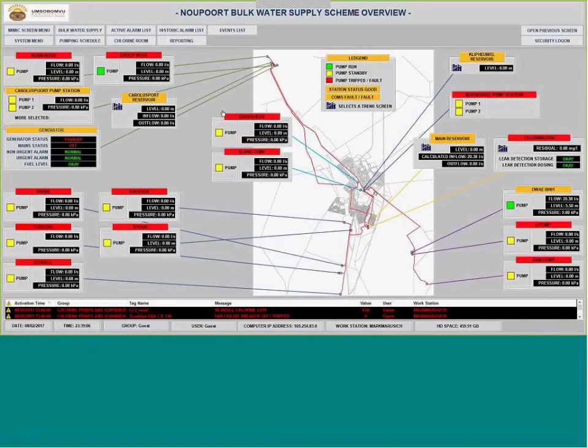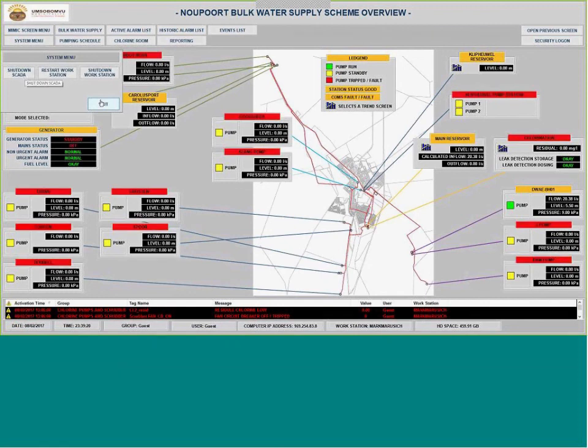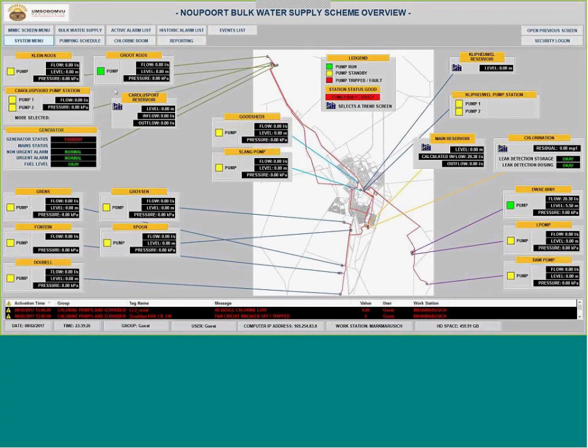in real time, we are currently busy with some reporting. It's not completed at this point in time because nobody can tell us what they want. We also created some very simple menu screens just to shut down the SCADA, restart the workstation, shut down the workstation, or whatever. The data is currently logged to a SQL database on site, and later on we will move the data to an off-site server for the client to do whatever they want with the SQL data in the database.